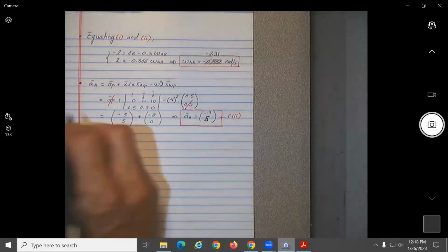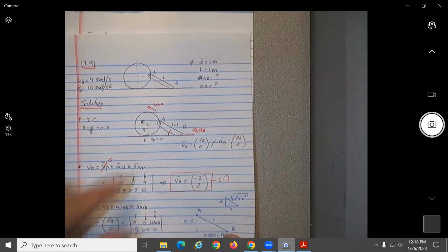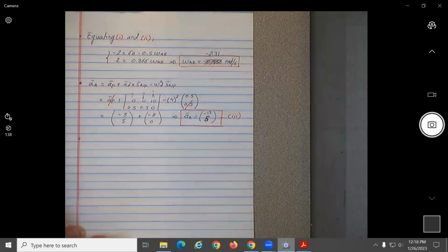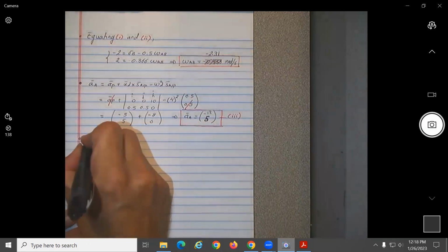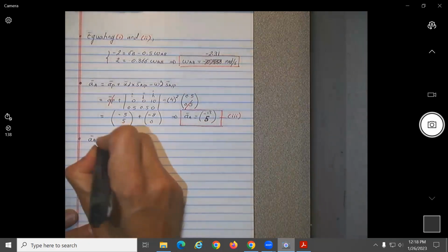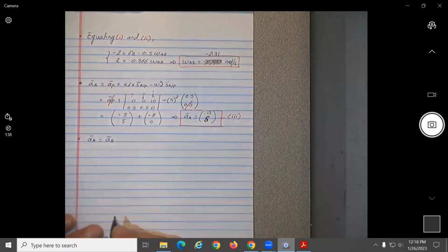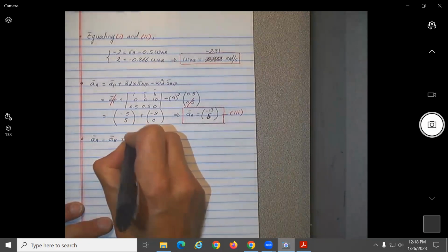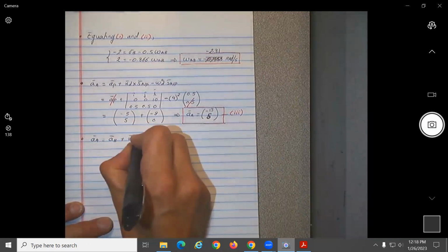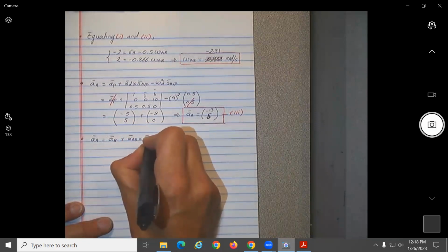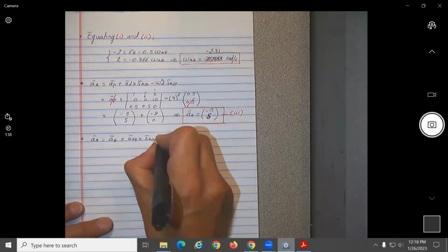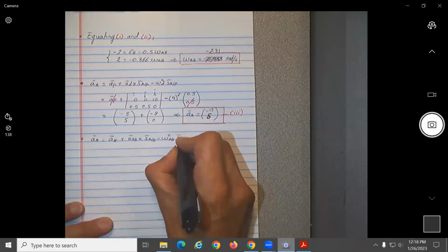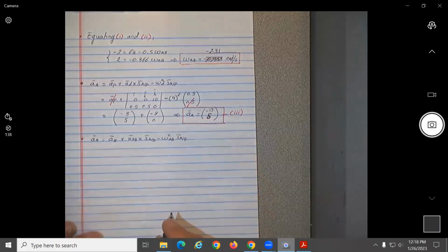All right, now we're going to calculate the acceleration of point A from point B, no? Let me slow down a little bit. I'm looking at the watch at the same time, so we want to make sure we finish. So acceleration of A from point B: A sub B plus alpha of the bar, which is AB, cross r of A with respect to B, minus omega squared AB, r of A with respect to B. I'm going to need your help here for sure with the calculations.